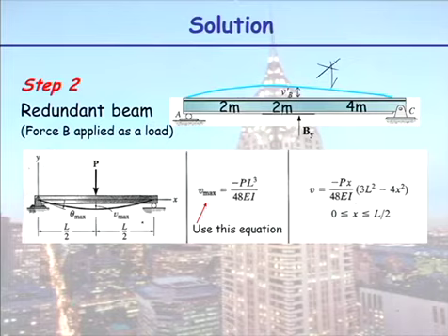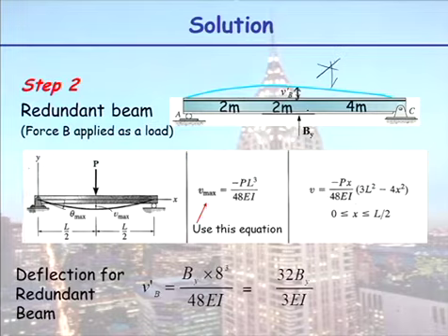The other piece of useful information for this problem is as drawn here. Now, as drawn here, V max, because it's symmetrical, gives you the deflection in the middle of the beam. And this is the general expression for V. Where do we want the deflection? We're looking for this deflection here, which is effectively in the middle of the beam. So we can now use the simple equation this time. So plugging in here, L is 8 metres, and we keep it in terms of By.